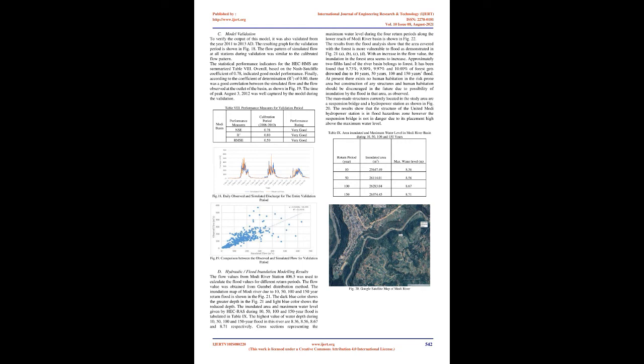Since the selected flow regime was subcritical, boundary condition was defined only at the downstream end of the river. It was defined by the normal depth, which is the slope of the river bed. The boundary condition at the junction was predefined by the software. After simulating the system in HEC-RAS, the results were obtained in the form of depth, velocity, and elevation of the water surface in the RAS Mapper window.